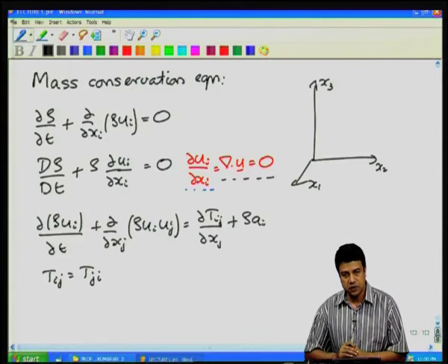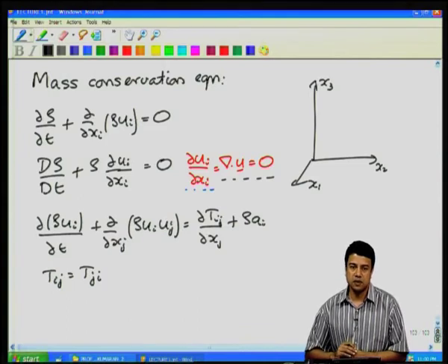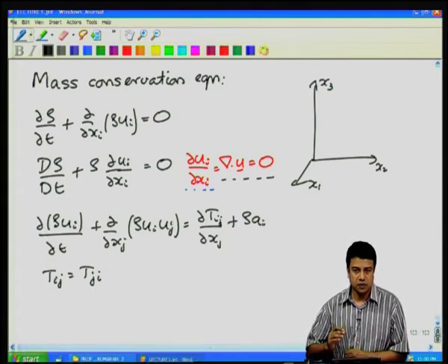And as with our derivation in the case of the rate of deformation tensor, where we separated it out into a symmetric, antisymmetric and an isotropic part. So, there was an isotropic part which was basically something times an identity tensor. Then there was a symmetric traceless part, a symmetric tensor which had the property that the sum of the diagonal elements was equal to 0, plus an antisymmetric part.